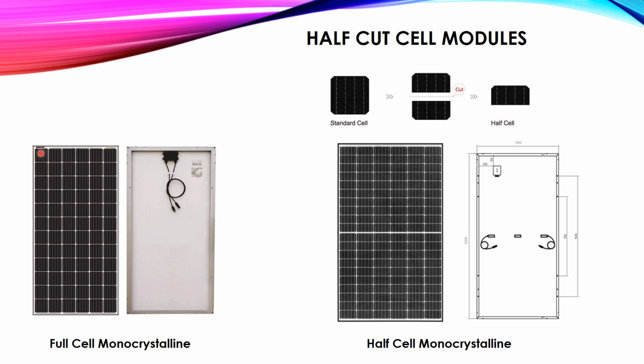So one bypass diode for one string. These two columns, this column and this second column, form one string, and we add to it one bypass diode. This column and this column, we make it one string and provide for it one bypass diode, as we will see in the next slide. Don't worry, we will understand the string and the number of bypass diodes. And here this one and this one, these two columns form one string and one bypass diode.